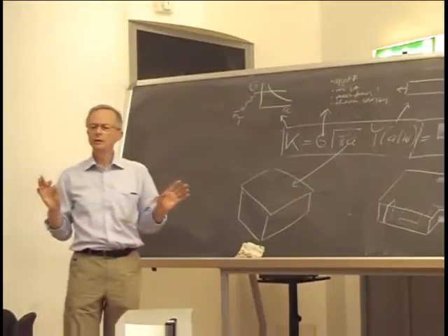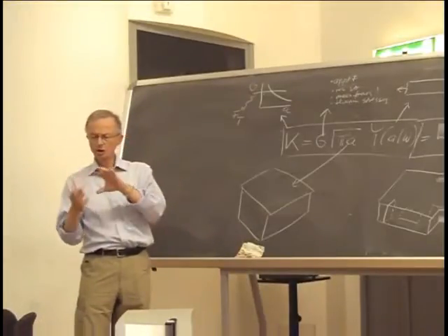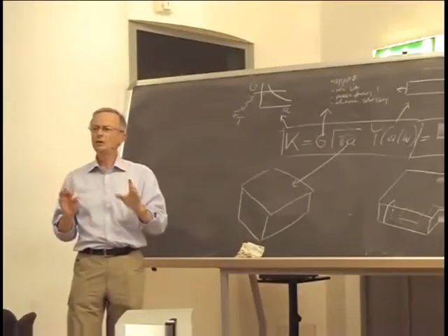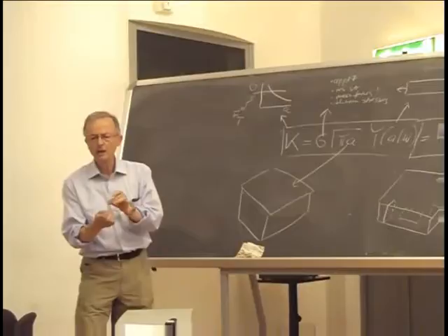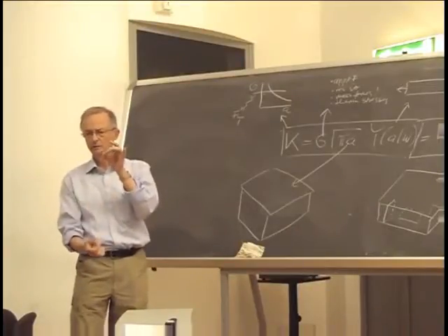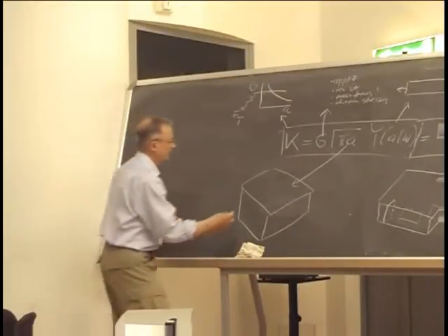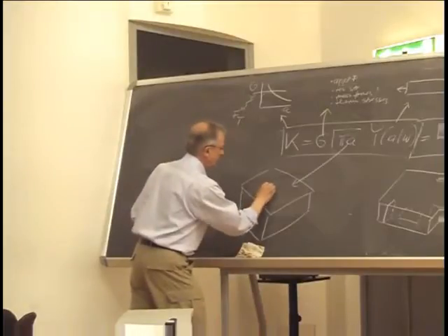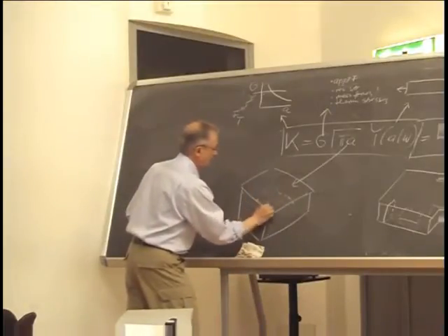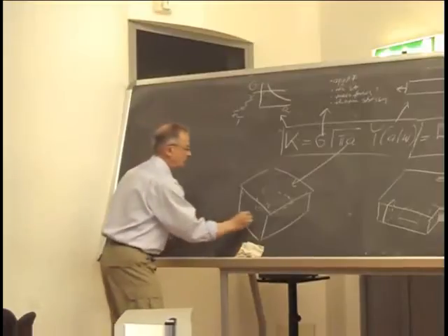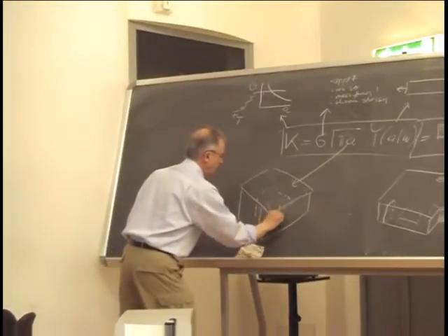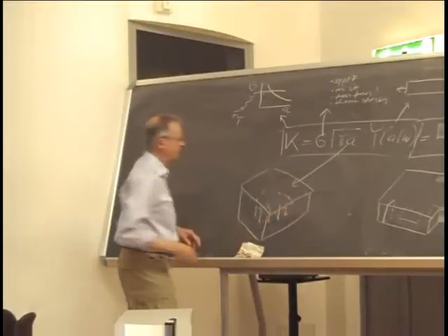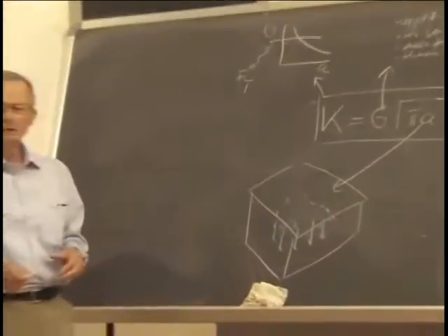I mean, you shouldn't be interested in the exact shape of the thing. What you need is a projection onto that plane that is perpendicular to the maximum stress. Okay, so you have something quite irregular, and you do the projection onto the plane of maximum stress or lowest toughness or whatever, and then I think you can get along with it.